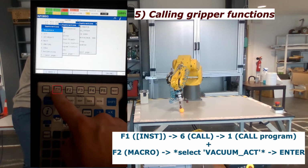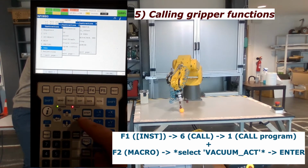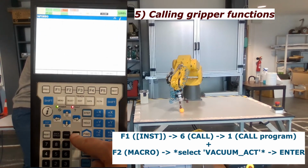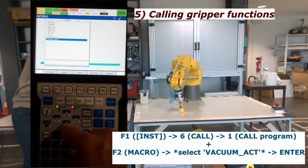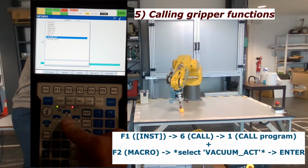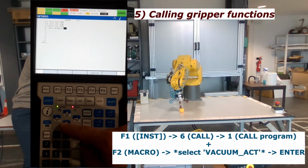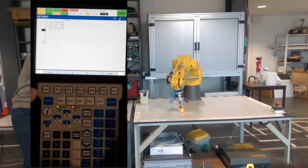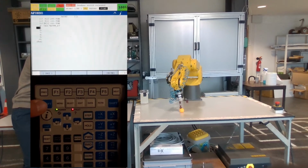For grabbing the ball, press the F1 key for choosing inst, then choose the 6th option with the name call, and then call program on the first option. Now we can see the list of all the programs. The vacuum activation is a macro program, so you should press the F2 key for seeing all the available macros. We should select the vacuum_act option and press enter. At this stage, the robot will pick up the ping pong ball.